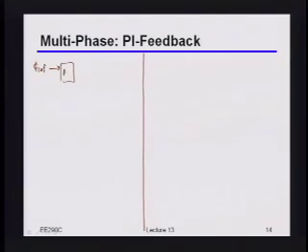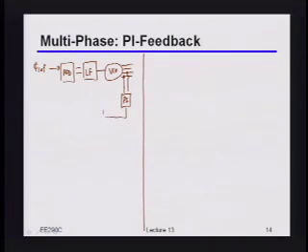We're still going to be essentially hacking things in the PLL. But this time, instead of mucking around with the charge pump itself, what we're going to do is take those multiple phases from the VCO, and this time I'm just going to put a phase interpolator. Instead of using that to directly generate the output, I'm going to use it to provide the feedback for my PLL. Where now again, this phase interpolator is of course controlled by the CDR control bits.